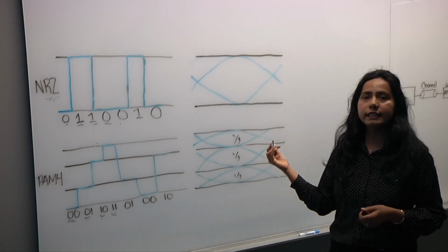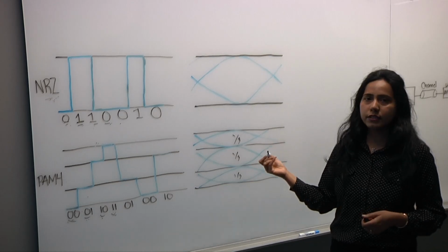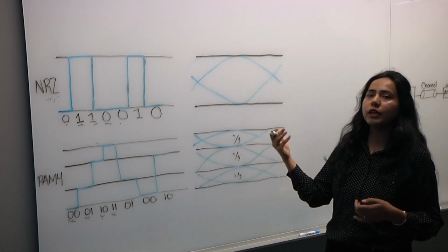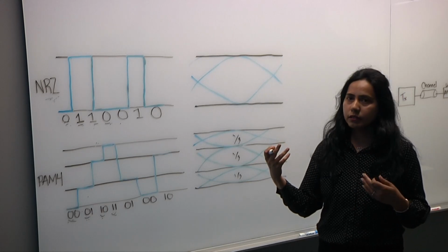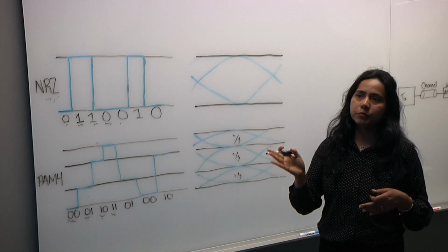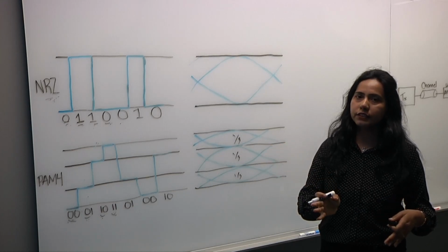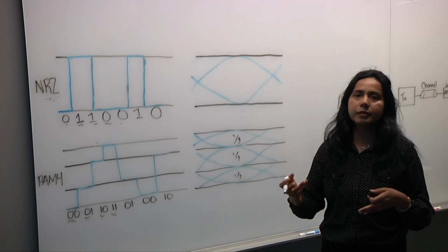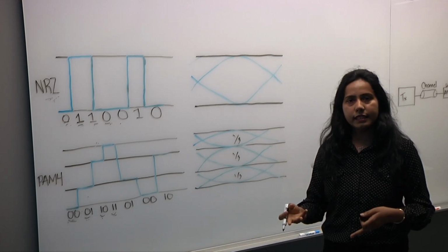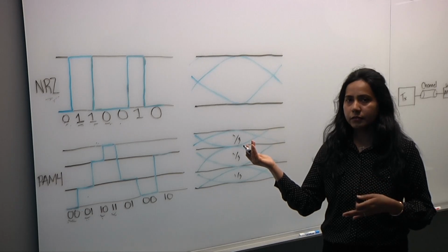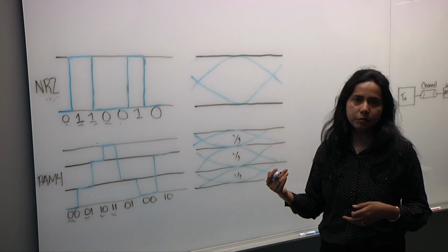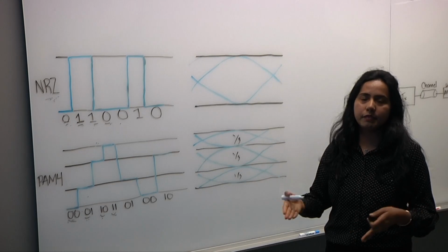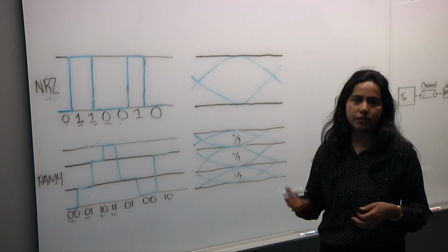Of course, for PAM4, we need the FEC, forward error correction, to make sure that your bit error rate is basically error free. So with PAM4, we have introduced the new concept called bit error rate, and before the forward error correction, you will have a certain amount of BER, which different standards have a different spec. For example, PCIe Gen 6 has 1E-6 as the spec, and for Ethernet it is 1E-4 for 100 Gbps. So that's where this forward error correction, although it has this latency aspect, is able to clear out that error in the system.